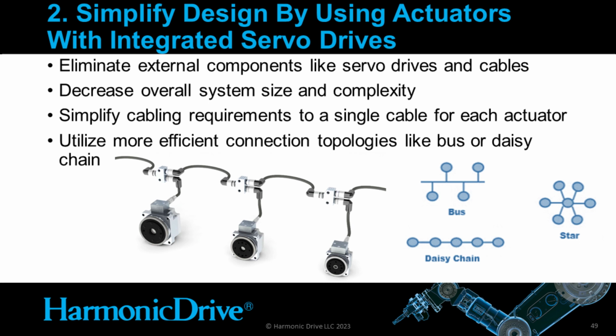The second tip I have is to simplify your design by using actuators with integrated servo drives. So eliminate external components like servo drives and cables from your system. This will decrease your overall system size and the complexity. You can simplify your cable requirements to a single cable for each actuator. And you can utilize more efficient connection topologies like a bus or a daisy chain.